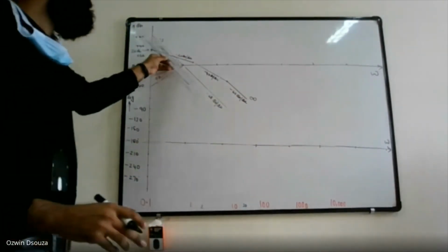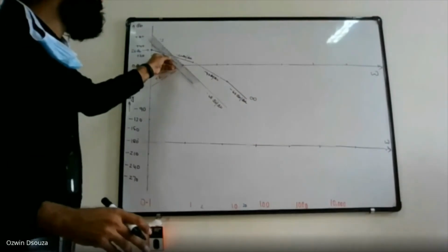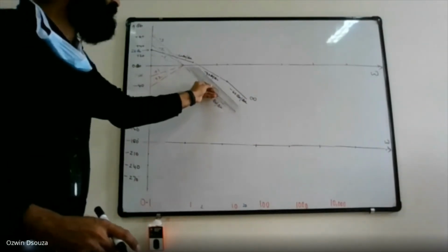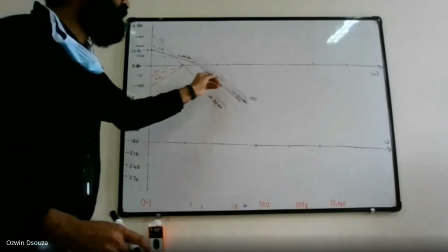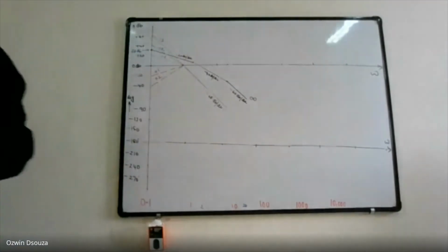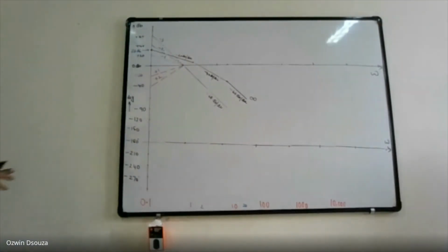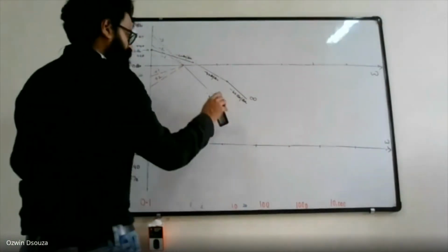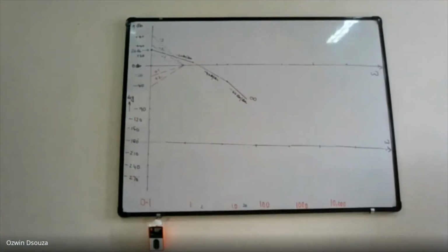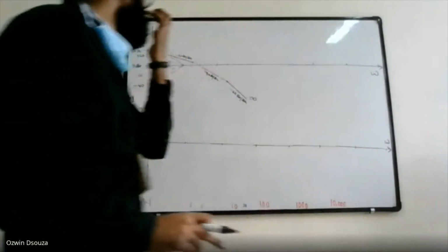I've just extended this minus 60 decibel per decade reference line, and then I just shifted my scale upwards so that this line is parallel to the reference line. Okay. Once the line is drawn, my purpose is served. So I will delete out the reference line. So that completes my magnitude plot.